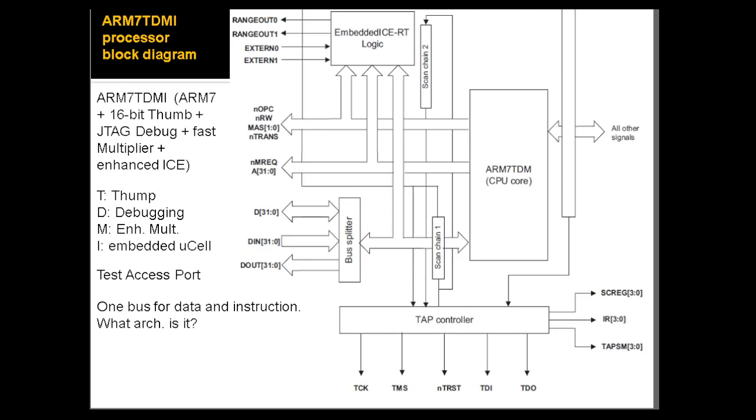Here is a little bit more about the architecture. I specifically wanted to go over some of the buses here that you have. So the ARM architecture is simply like, this is a CPU core. This could be your Cortex CPU, and it communicates with peripherals over buses. And I would like to just mention, for example, that the bus width is 32 bits. So you are moving data back and forth in 32-bit values. So keep that in mind. So we've learned so far that the registers are 32 bits and the buses are 32 bits.